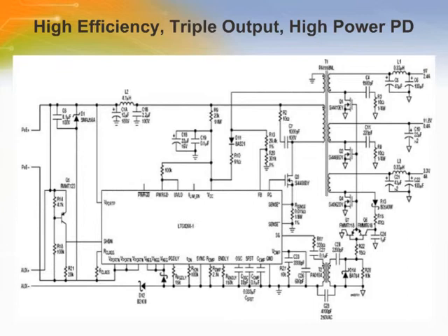The small supply of the LTC4268-1 utilizes an isolated flyback topology with synchronous rectification that requires no opto-isolator, lowering the parts count. This circuit gives efficiencies at load of 83% when powered from a power sourcing equipment and over 85% when powered from an auxiliary supply.